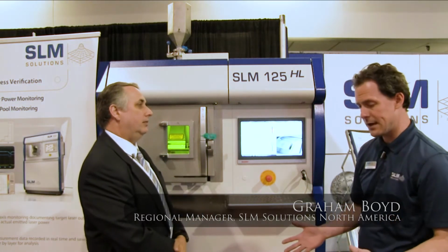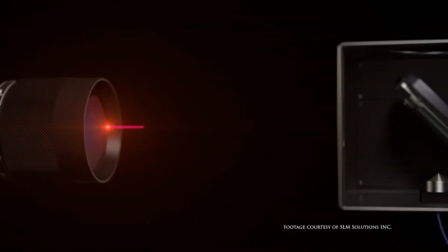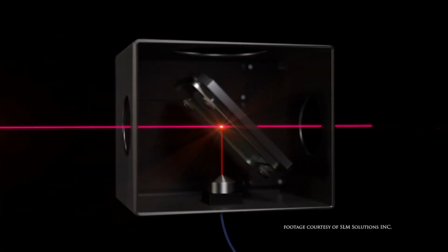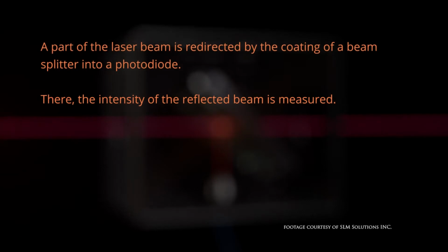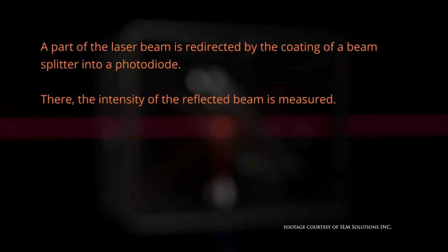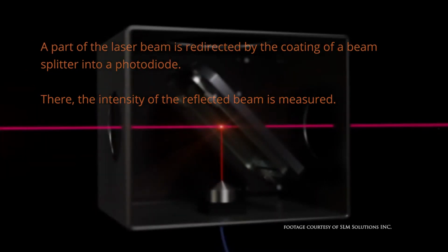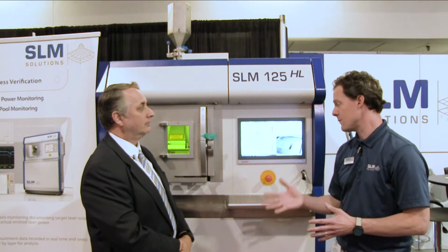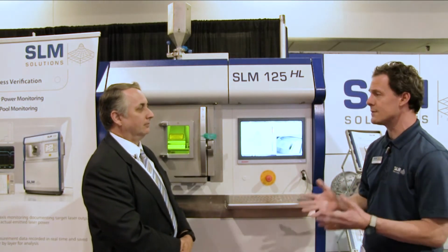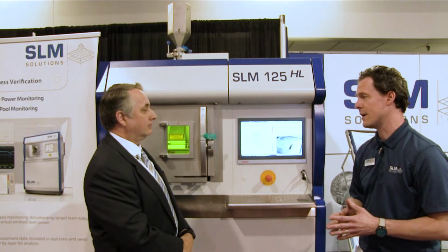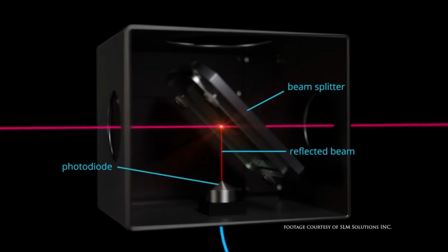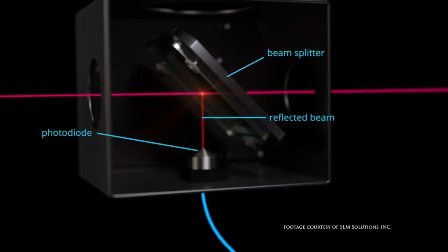Yeah, we're really excited. We have introduced a couple new technologies at SLM, our laser power monitoring as well as melt pool monitoring, to help folks with quality part verification. These are capturing, with respect to the laser power monitoring, real-time capture of the laser power energy as it comes off the laser through a beam splitter, as well as, in our melt pool monitoring, the actual thermal emission when the laser power hits the powder bed.